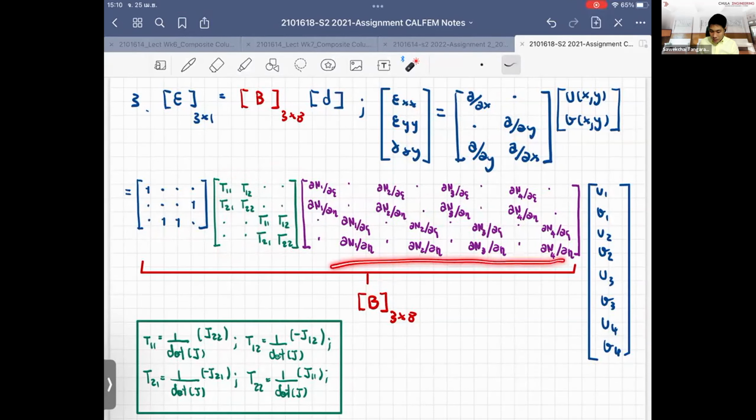And the length of them is about how you take the first derivative of the shape function. This is written in terms of the natural coordinates, right? So we want to transform two of the coordinate systems, so we have to use this. On the other hand, if you don't want to transform them, you want to use just a standard quadratic element, you derive everything in terms of the real coordinate x, y. So you don't need to use this, right?